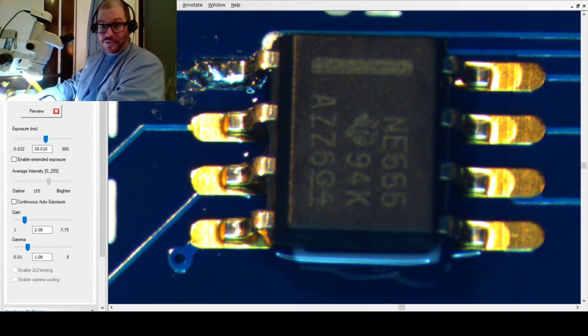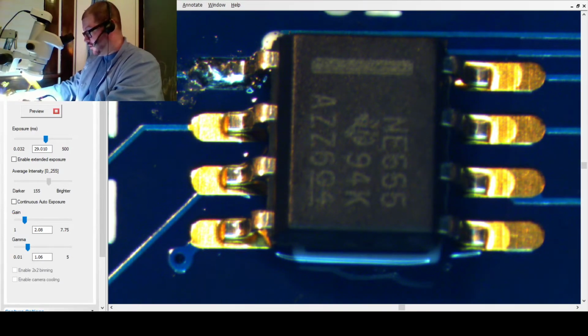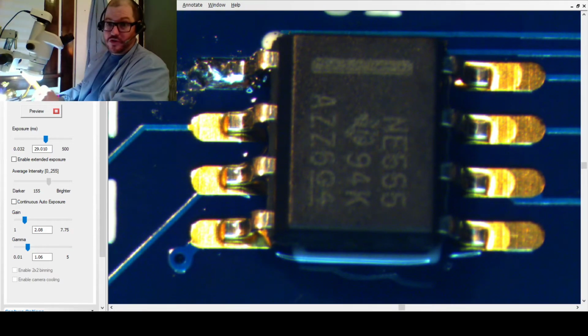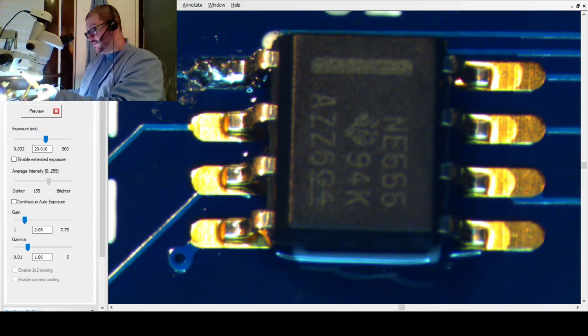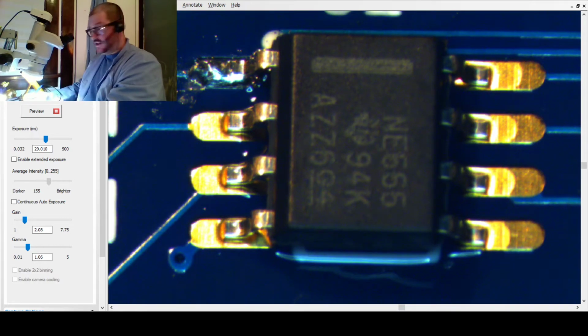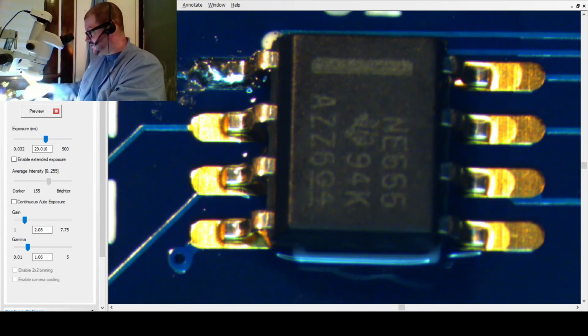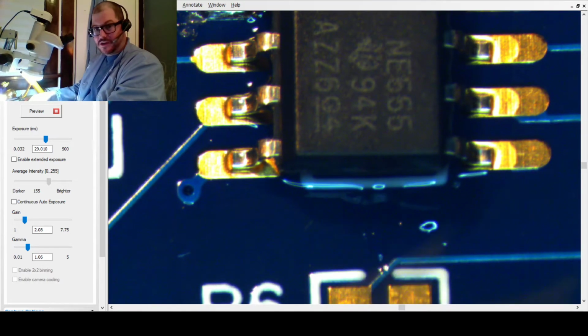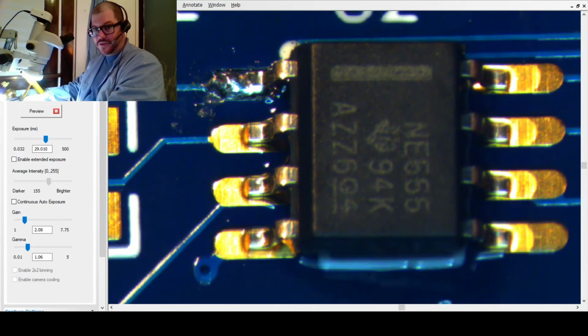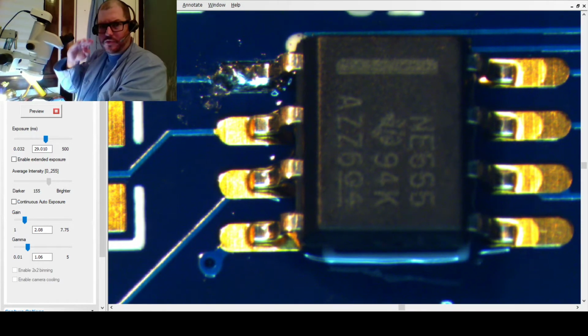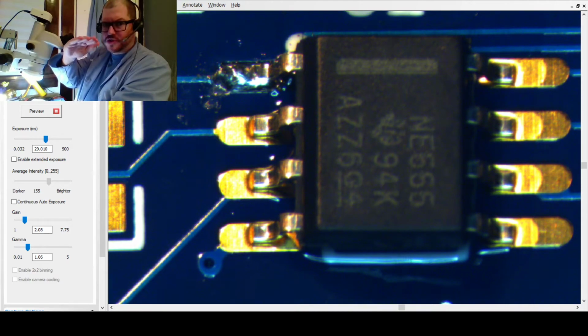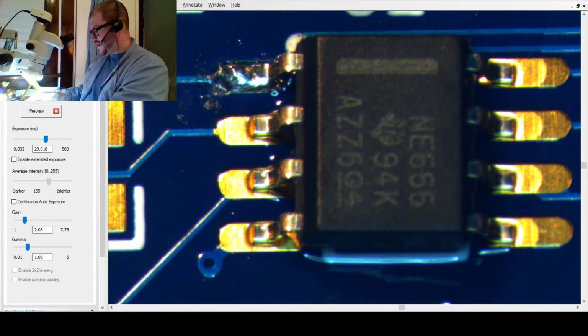So now at this point, the leg is soldered a little bit more into its place. What I'm going to do now is tin all the rest of the legs of the chip, because now at this point, essentially, the chip is mounted into place. One pin is mounted, and all of the rest of the pins are pushed flush against the printed circuit board pads that we have.